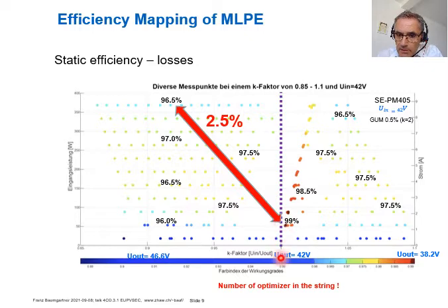If you have input-output 1 and you increase the power, you see here the ohmic losses of these DC-DC converters, and you end up with about 1 or 2% less efficiency at nominal output condition in the best case.